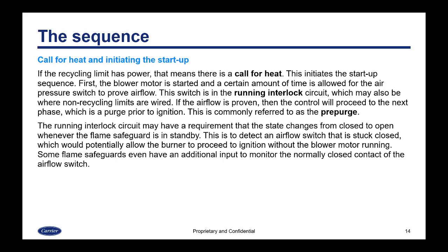The running interlock circuit may also have a requirement that the state changes from closed to open whenever the flame safeguard is in standby. That is to detect an airflow switch that is stuck closed, which would potentially allow the burner to proceed to ignition without the blower motor running. What that means is that you don't jumper out the airflow switch, basically, or that it actually does change state to prove that it works. Some flame safeguards even have an additional input to monitor the normally closed contact of the airflow switch. And if they don't have that, they just monitor that the airflow switch input is not closed.